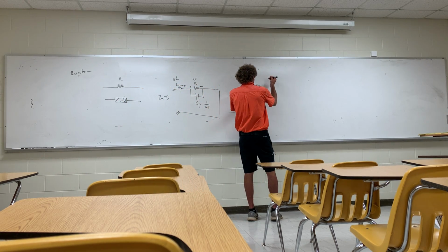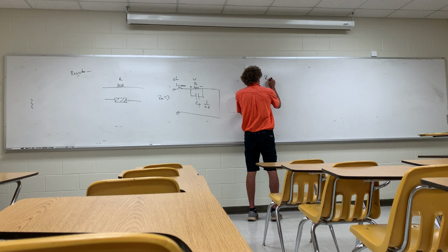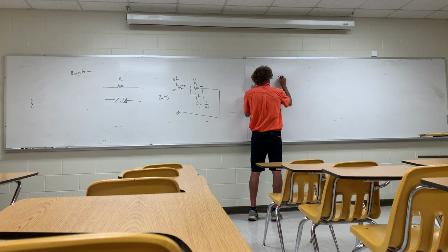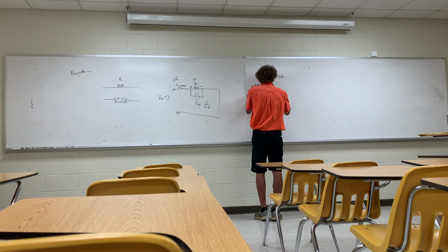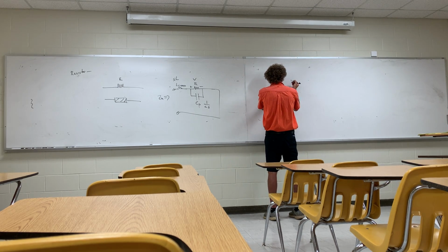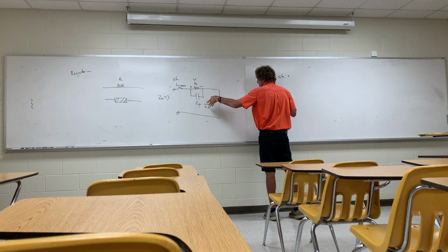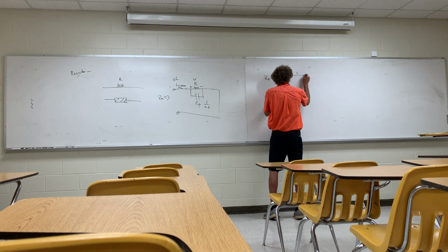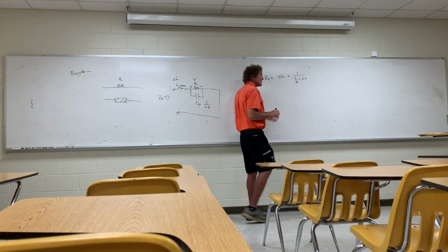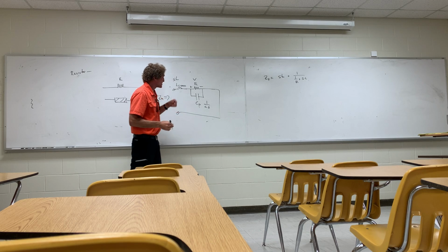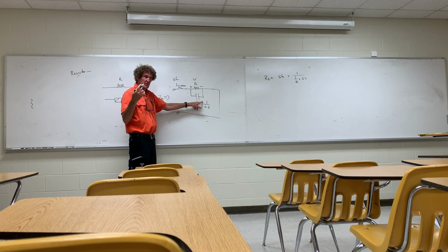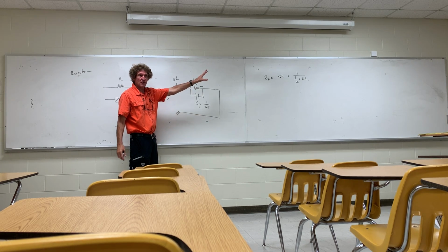So we could say the actual Z of the resistor itself would be S times L. And I'm not even going to put L lead here, it's assumed. Plus the parallel combination of the resistance and that. So it would be 1 over R plus SC. I just took 1 over resistance plus 1 over the impedance of that, which would be 1 over CS, which is just CS. Do y'all follow me on that, guys? Everybody follow me how I wrote that and why I did it?